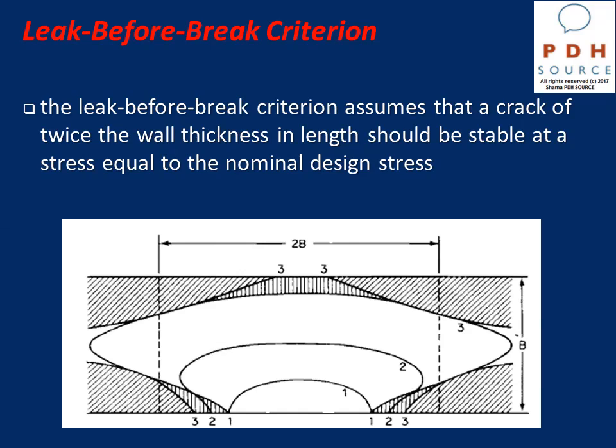And the objective here was that the surface crack could grow through the wall and the vessel leaks before any fracture occurs.